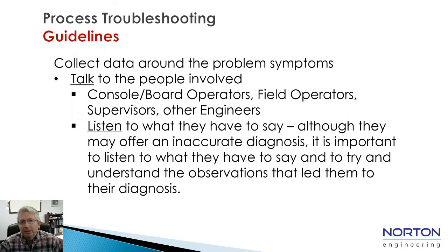It's also very important that you talk to the people who are involved. Talk to the console and board operators, the field operators, supervisors, other engineers, subject matter experts. You need to listen to what they have to say. They may be jumping to conclusions and jumping to inaccurate diagnoses of what the problem is, but it's important you understand why they're making those leaps and trying to come up with the diagnosis of what the problem is. Their description of the symptoms may be very, very helpful to you so that you could try and understand what may be really going on.